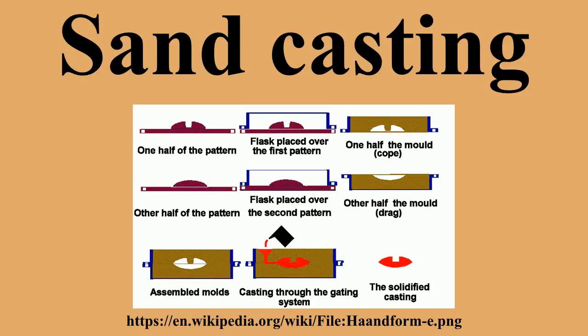The sand also has the dimensional instability associated with the conversion of quartz from alpha quartz to beta quartz at 680 degrees Celsius. Often additives such as wood flour are added to create a space for the grains to expand without deforming the mold.